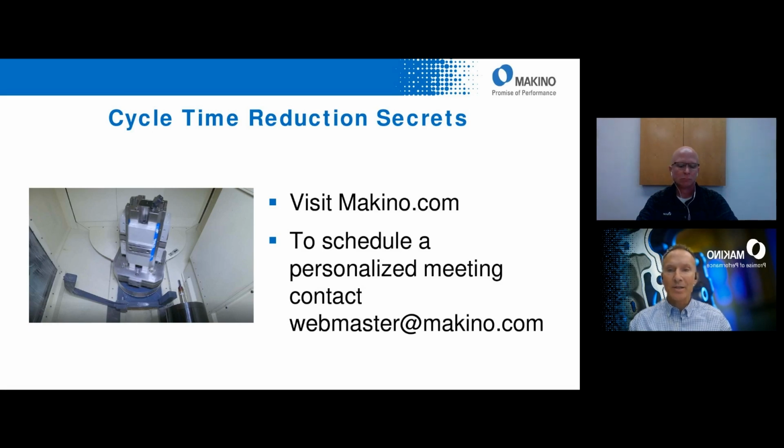You talked about in this demonstration how we were looking at the cycle time savings. After you went through the demonstrations, you had macro variables that showed the cycle time we were saving. This question is around that. How do you use macro variables to record cycle time? We talked about that in part one a little bit, but just a brief description here. Yeah, you use the system variable 3001.